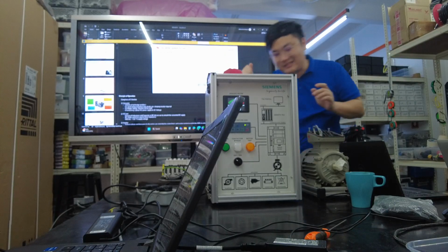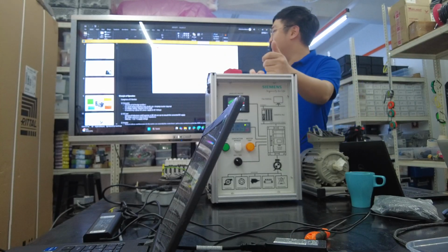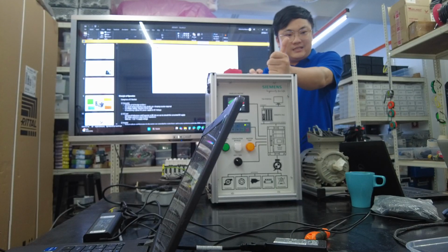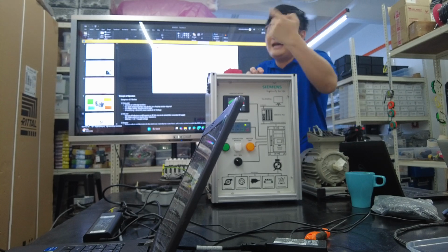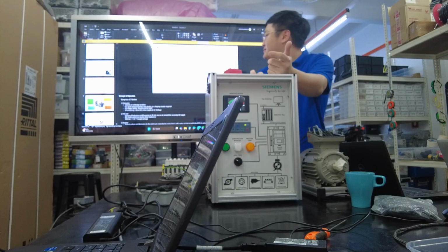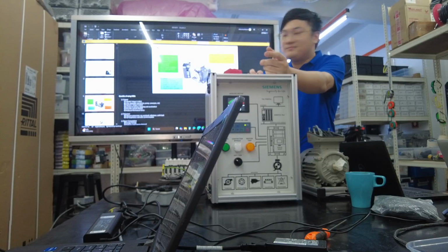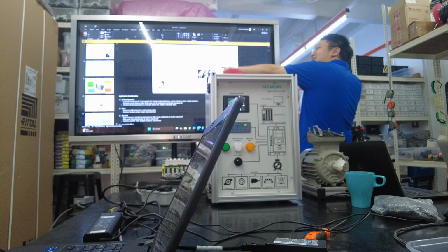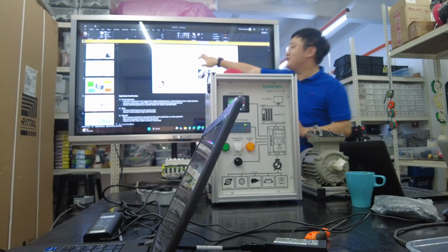They will just provide some harmonics back to your power line. Your harmonics will also affect your power factor. THDI, we call it total harmonic distortion current. It will interrupt the power factor. Definitely, a low power factor will cause higher consumption. We don't want to go too deep, so they will have a harmonic filter. Okay, this is the application, consumption, the limit and the solution.